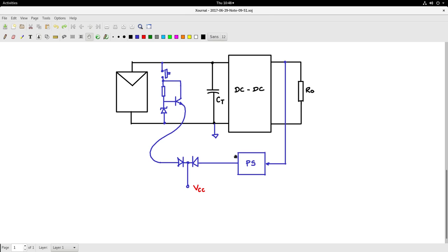Now there will be one or two windings for gate drive. So let us say if there is one power semiconductor switch here with a floating source, then one of the windings will be used for gate drive of this particular semiconductor switch in the main DC-DC converter. So therefore housekeeping power supply design itself is very, very important, and one has to give a lot of thought to it.